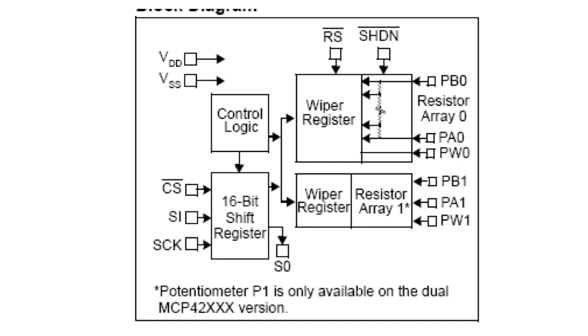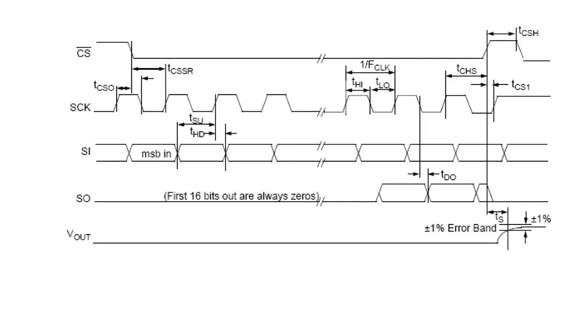So inside of the DAC, you've got a little shift register that's taking in the chip select, serial input, and the serial clock, and then gives you a serial output. And this is probably too much detail by half for a timing diagram, but it essentially shows you that you have to take the inverted serial chip select and assert it low in order to select the chip. And then the serial clock comes in and proceeds to strobe in the data as it comes in through the serial input.